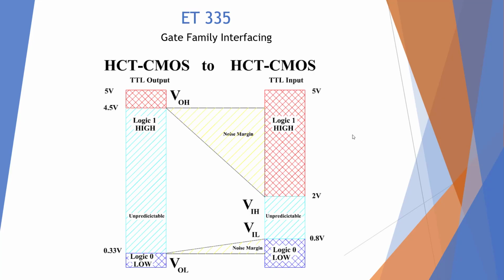Here I'm showing an HCT CMOS to HCT CMOS. HCTs are directly compatible with our standard TTL. So they're a CMOS device, but they're set up to communicate properly with a standard TTL. So this is our direct replacement.